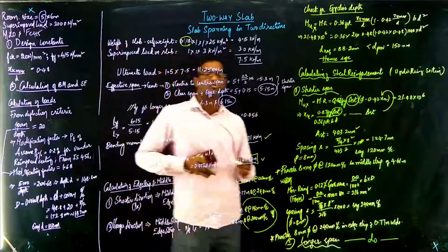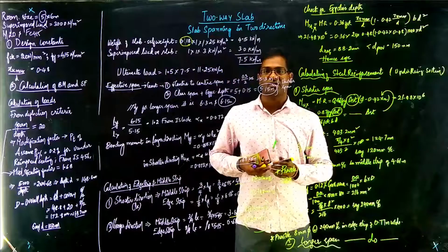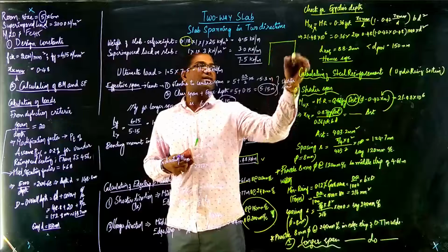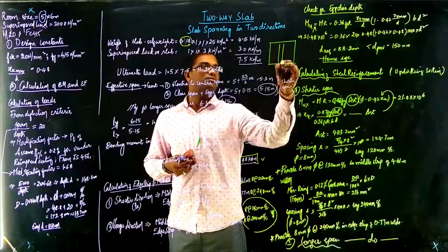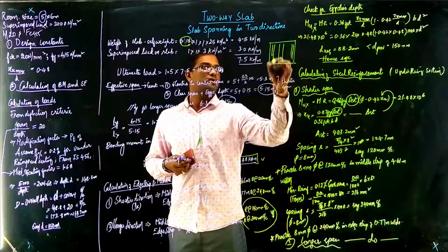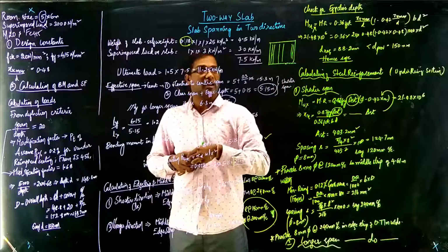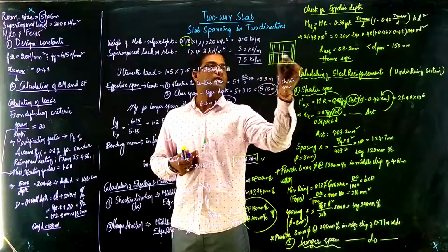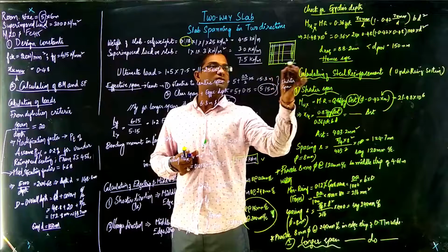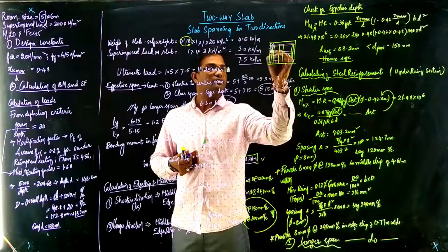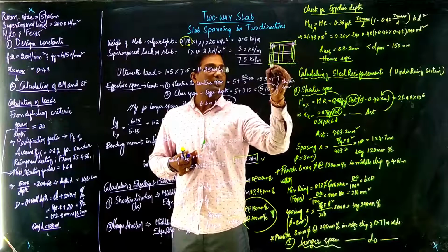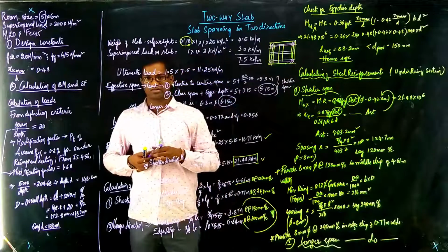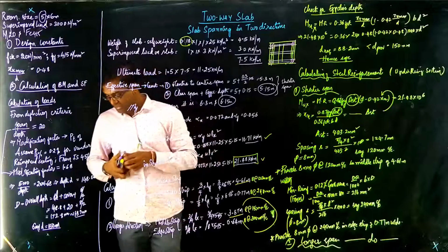Right? In the next step, we have to calculate the torsional reinforcement. Right? Torsional reinforcement is provided at the corners. Now you have calculated the steel in the middle strip, in the edge strip, in short direction, and in a similar way, you have calculated the steel in longer direction, that is middle strip and edge strips. You also need to calculate the corner reinforcement because corners are held down from lifting, so you have to provide this mesh at 4 corners, right? So we will calculate this in Annexure G.